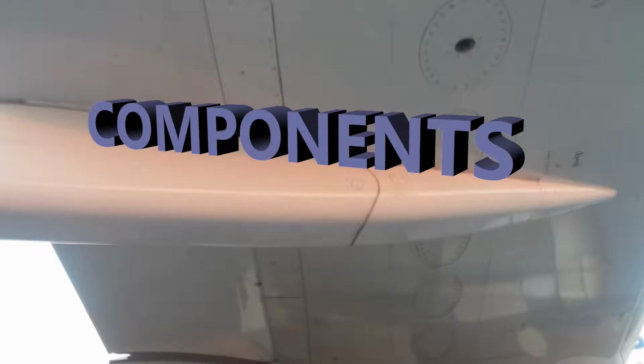As far as accuracy on the indication system, it's accurate to plus or minus 1% of the maximum tank capacity. Okay, and also plus or minus 1% of the actual FOB, fuel on board. Okay, and that's when the aircraft is on the ground between a certain pitch and roll.